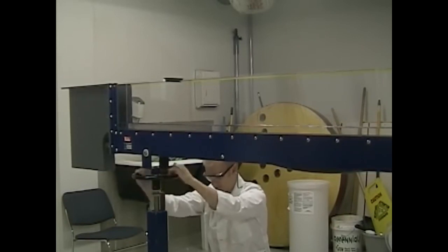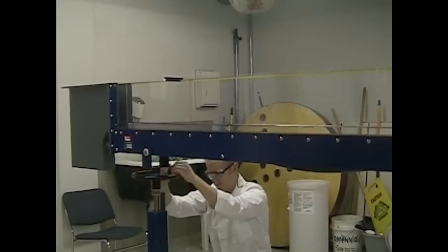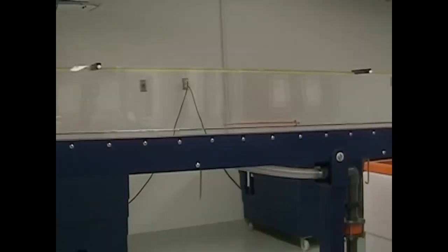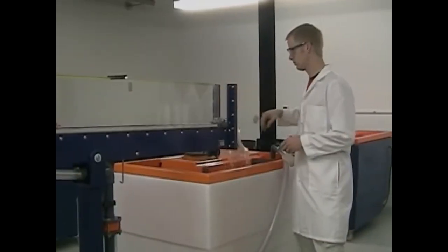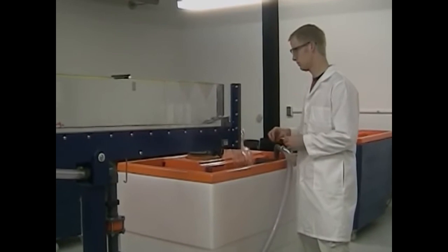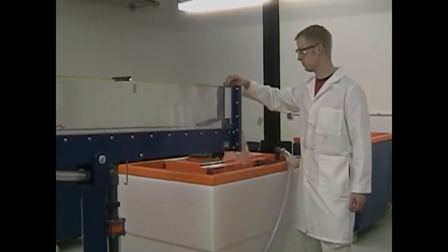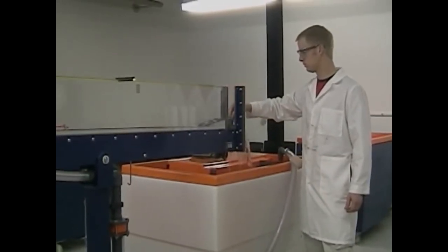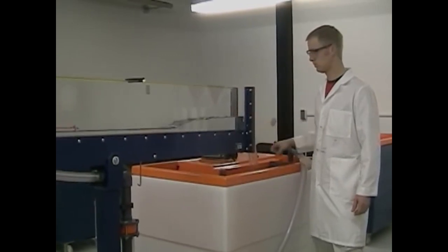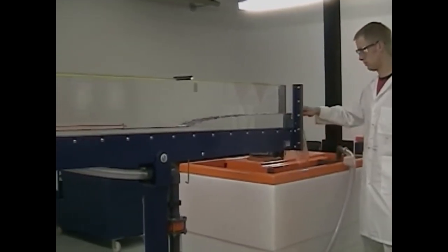You're right, the critical depth does not change since it is only dependent on the flow rate and geometry, and neither was changed. We can see that increasing the flume slope has decreased the normal flow depth, such that we have supercritical flow. Since we already have supercritical flow, all that we need to do in this case is cause subcritical flow downstream. This is done by inserting stop logs at the outlet.